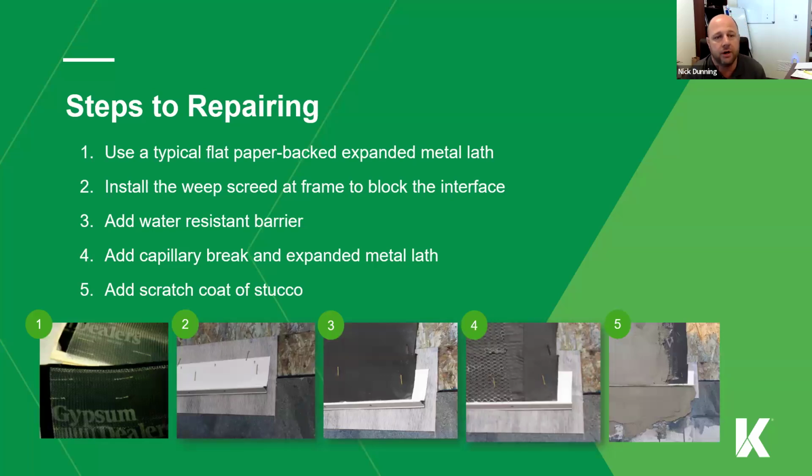We're working on a plumbing project right now where the city inspector approved 4 units that didn't have fire tape around the PVC, which is a huge fire violation. And the owners were a little upset that our inspector said, no, you have to open the wall. I have to see it. And he uncovered this. Their argument was, well, the building inspector signed off. So just relying on building inspections doesn't work. Now, there are great inspectors out there.